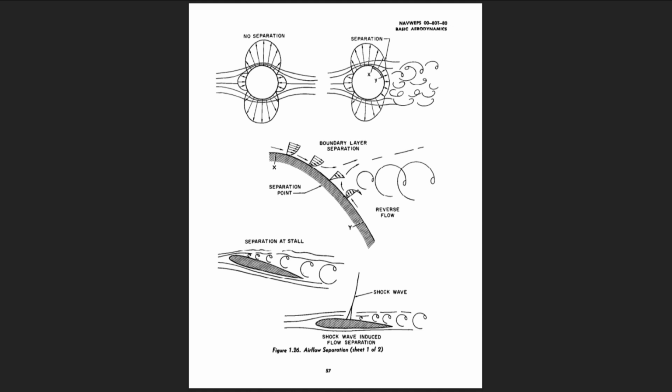If the boundary layer does not have sufficient kinetic energy in the presence of the adverse pressure gradient, the lower levels of the boundary layer may stagnate prematurely. Premature stagnation of the boundary layer means that all subsequent airflow will overrun this point, and the boundary layer will separate from the surface. Surface flow which is aft of the separation point will indicate a local flow direction forward toward the separation point, a flow reversal. If separation occurs, the positive pressures are not recovered and form drag results. The points of separation on any aerodynamic surface may be noted by the reverse flow area.